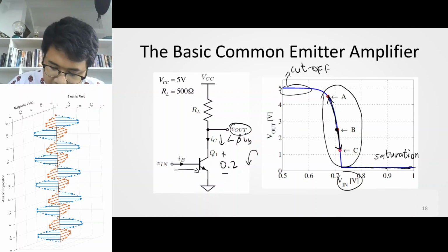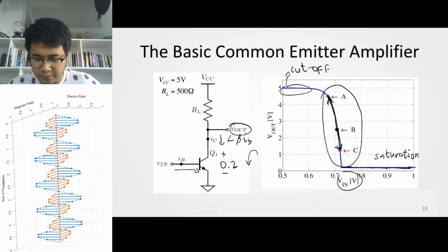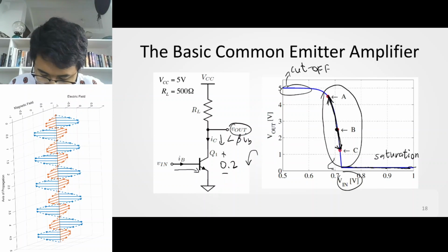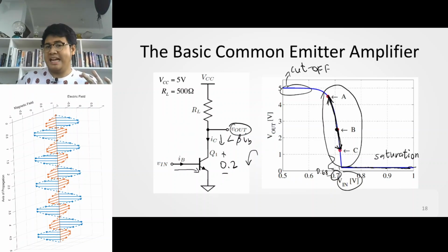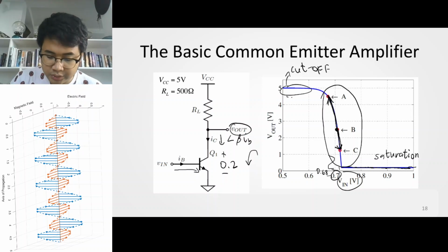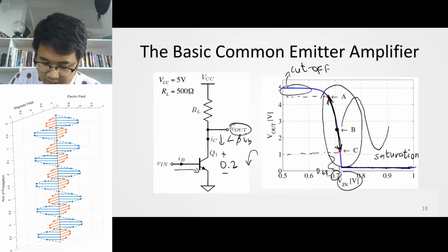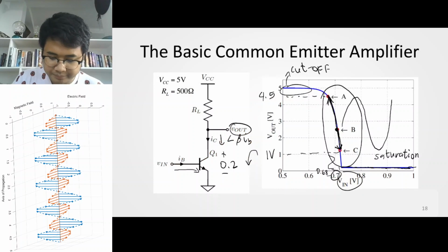Right? So your signal is fluctuating here, fluctuating towards this one. Okay, so your Vin is basically fluctuating between 0.68 to 0.7 maybe. So that small fluctuation only in the voltage, the effect of which is that your output voltage has a fluctuation from B to A towards C right here, and fluctuates from 4.5 volts to around 1 volt.